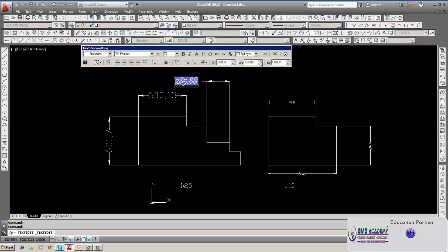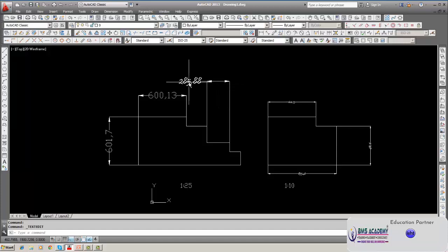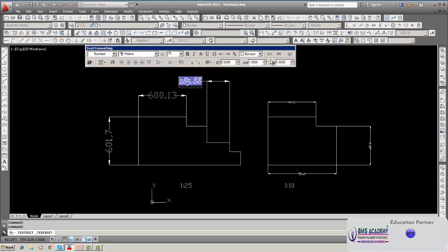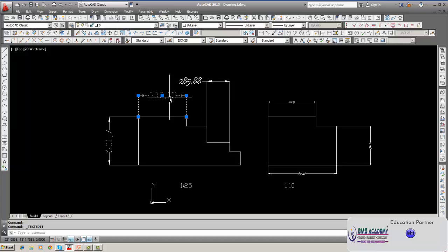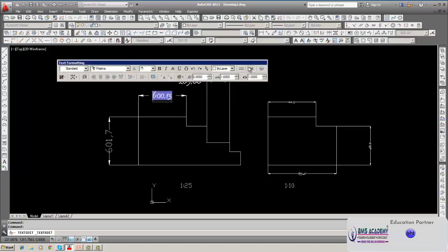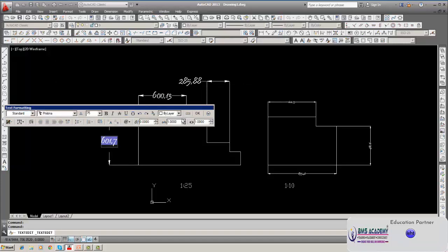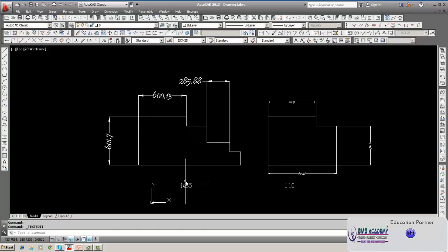Different fonts here. So what we have to see, we can change like clicking, but it will automatically get the same thing. You can change like this. You get changed to the same, but we want to maintain the same earlier one. So if you want to do that, you select another. This relates to font. Font remains the same in both style, ISO 25 and ISO 10. Fonts are the same in both. So once you regenerate, it automatically picks up this.